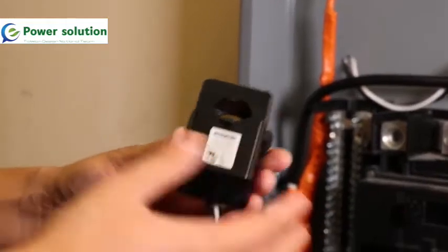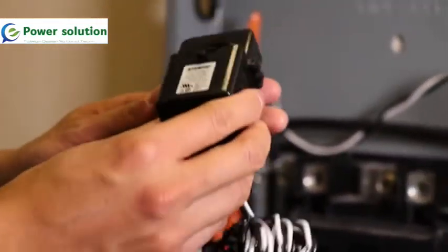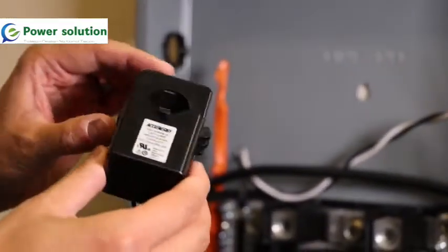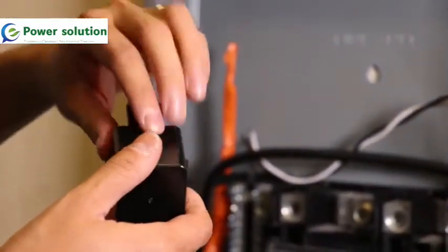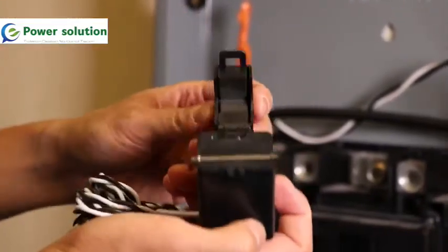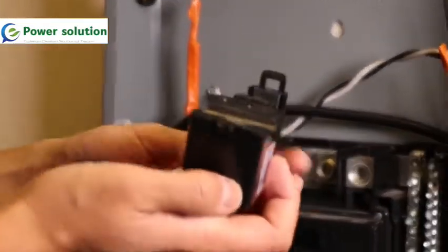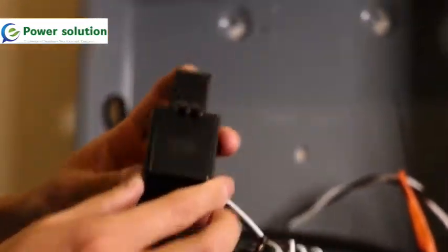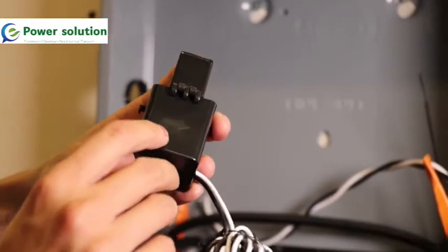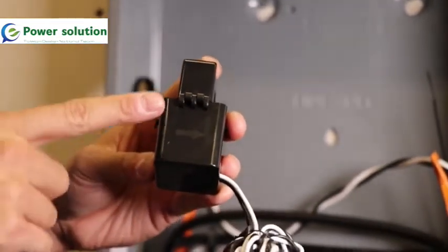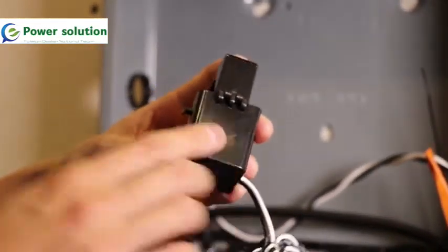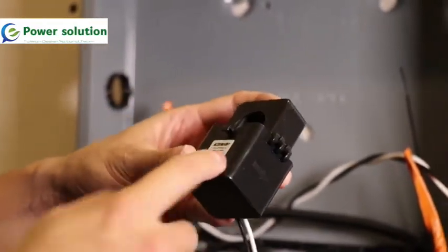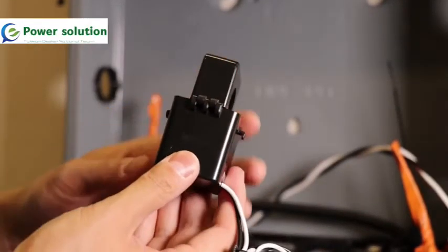In your kit, if your panel has larger loads, you'll have one of two types of off-the-shelf CTs. One is an AccuEnergy split core current transformer. There's a tab on the side that you pry open, and there's a hinge, and your current goes through this clamp. There is an arrow indicator on this. This arrow also goes in the direction of the current, so be sure that this arrow goes the same direction as the load, and the label here goes towards the source of the current when installing.